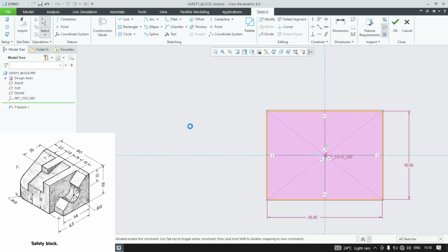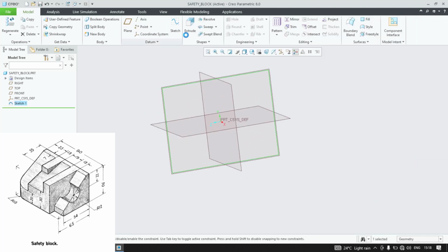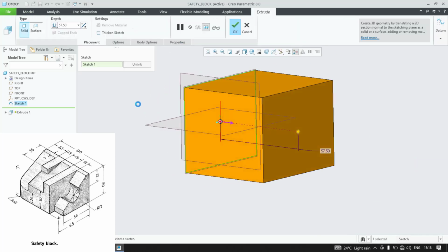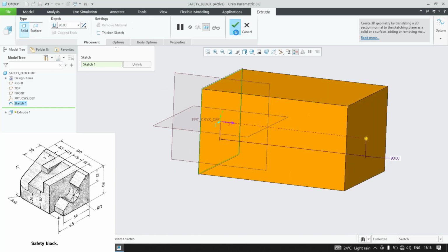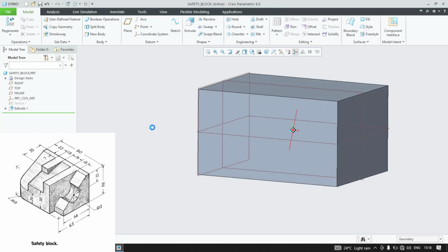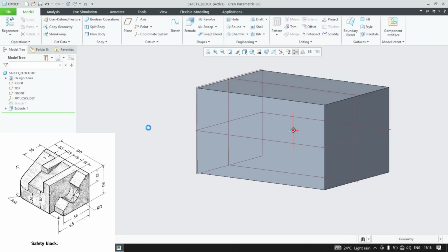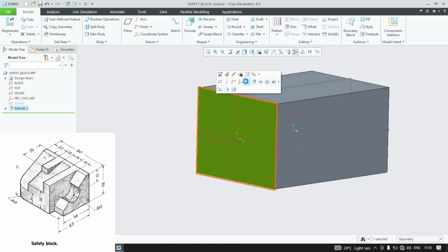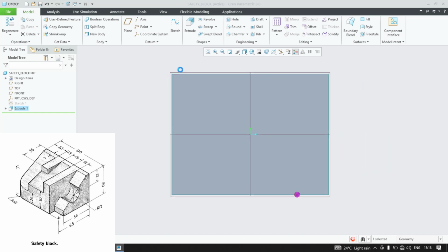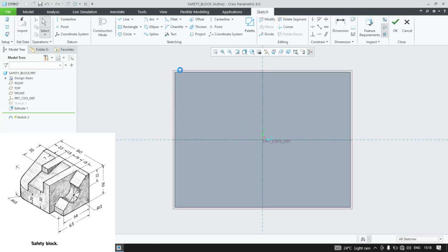Okay. So up to 90 mm I need to extrude it. So I'll just simply click on the green check and extrude it to 90 mm. Yep. So next thing is I need to start with the particular face. This time I'll start with this one. In the previous sessions I had gone through that side, but to avoid the complications, this is the best way.